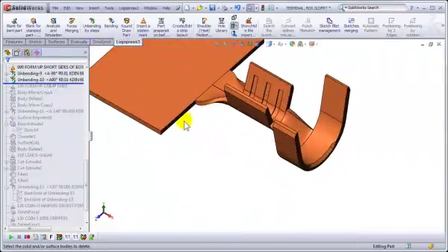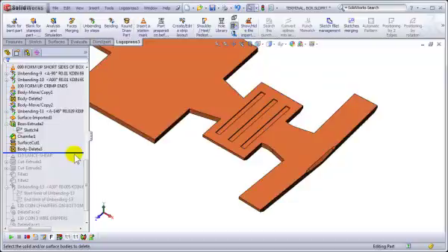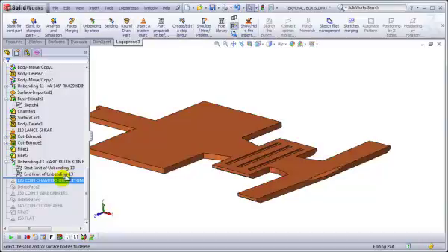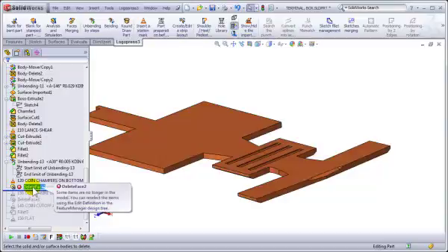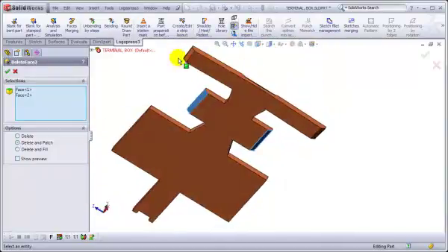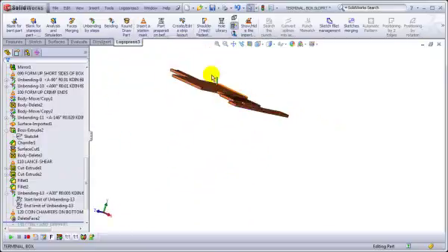So we're forming up the crimp ends like so, and then we show it in the lance shear position after that's flattened, and then coining the chamfers on the bottom. And then where we got rid of the chamfers here, we need to delete these two because these are new, so it didn't recognize them. There we go.